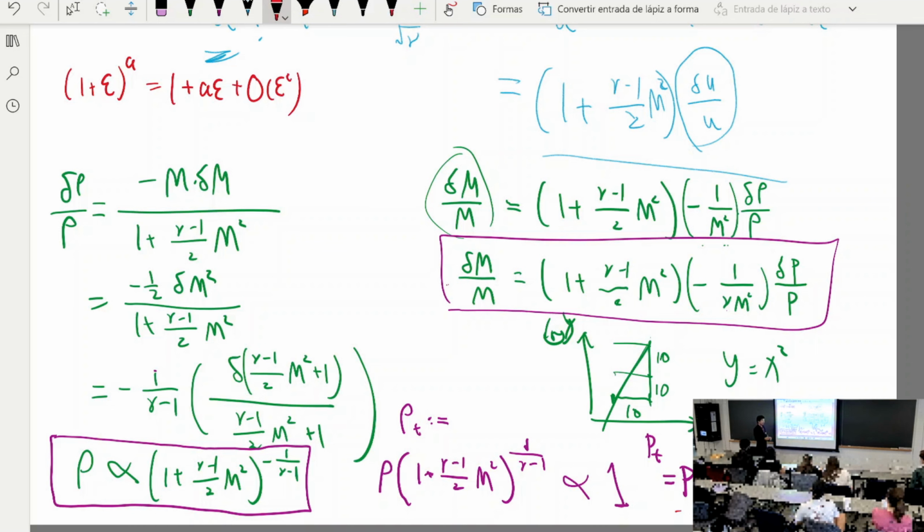And that you can just derive. If you look at the difference between stagnation pressure in this definition and the static pressure, you're going to get exactly half rho u squared. Okay? I can do the derivation for you. So at Mach very, very small, pt minus p would be equal to p times half gamma M squared.